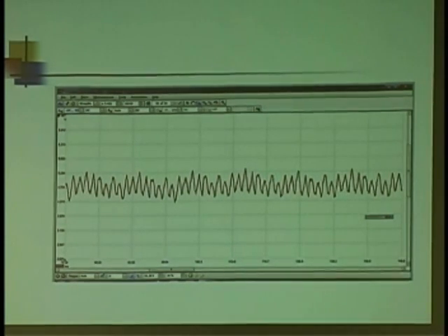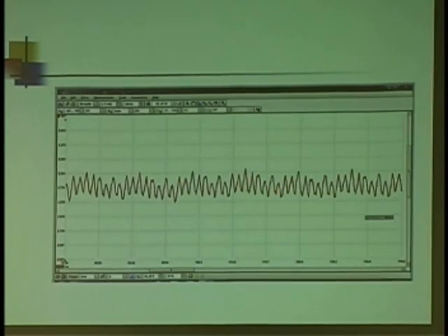Okay? Now if I saw any of these that were gone or really flat or really hashy, wouldn't that be an indication of severe wear between the brush and the commutator strip? The fuel pump may be operating today just fine. Would I be out of line if I showed that to my customer and said, you're good today, but this thing's near the end of its useful life, you might want to think about replacing it before you get stuck on one of these wonderful highways you've got around here?